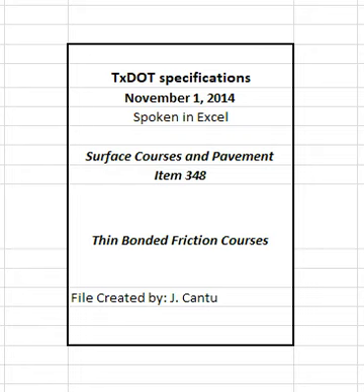4.4.2.2.3 Conditional approval of JMF1 and authorizing trial batch. The engineer will review the contractor's mix design report and verify specification conformance of the mixture and component materials. The engineer will grant conditional approval of JMF1 within 2 working days of receiving the complete mixture design report, JMF1, and all required materials. The engineer will determine the Micro-Deval abrasion loss in accordance with Section 348.2.1.1.2, Micro-Deval abrasion, unless waived.